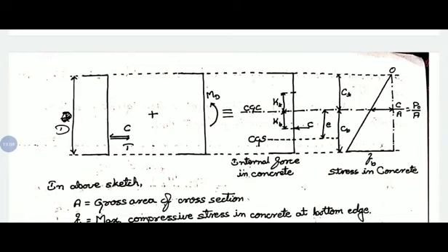The tensile stress comes from the tendon, which in turn applies compressive stresses on the section, and here we are considering only MD, the moment due to dead load. CGC is the centroid of the concrete section, and CGS is the centroid of the steel or tendon. The distance between those two centroids is the eccentricity.